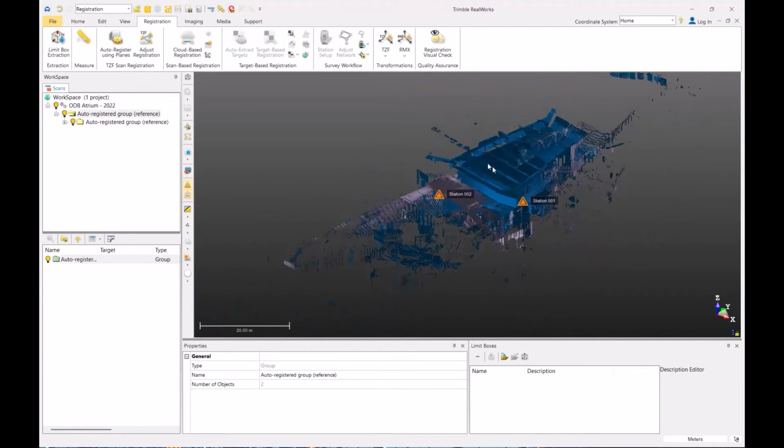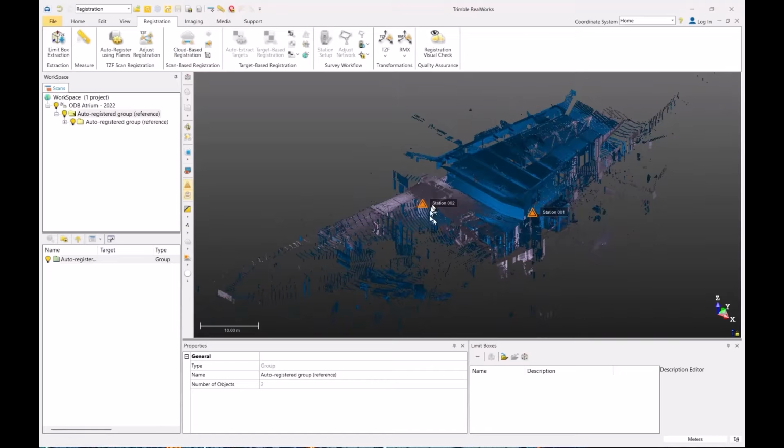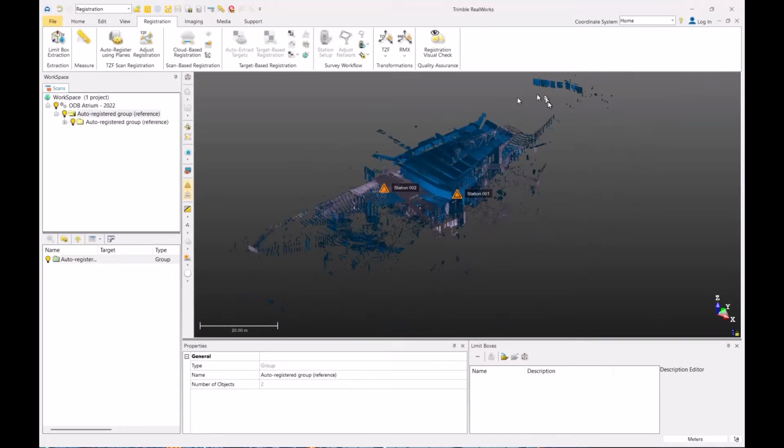And so for now, actually, we don't really have to do anything right here. But you'll see my preview. You'll see the 2 stations right in there. And I could actually now refine a point cloud right in here. For example, there's a bunch of ghost points that came in through reflections, and a clean point cloud, you would want to remove those. So anyways, that's the registration part in a very, very small nutshell.